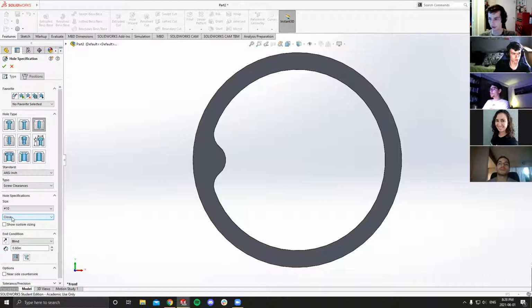The tighter the clearance on your screw, the less slop there is. But not everything has to be super precise in terms of locating, and this screw isn't really doing any locating, so we don't care if there's any slop in that hole for the screw to move around. All the screw is doing is clamping this mid ring, and you'll see what I mean in a couple minutes.